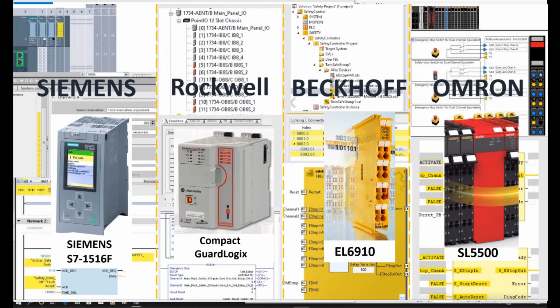For example, you need to use that buffer: put the safety signal, transfer it to that buffer, and after that, transfer the buffer signal to the standard logic. Or reversely, if you need to transfer a signal from the standard PLC to the safety PLC, you transfer that standard signal to the buffer, and after that, transfer the buffer signal to the safety logic. But it doesn't mean it creates trouble for you. Actually, it can help you isolate the standard logic and the safety logic.